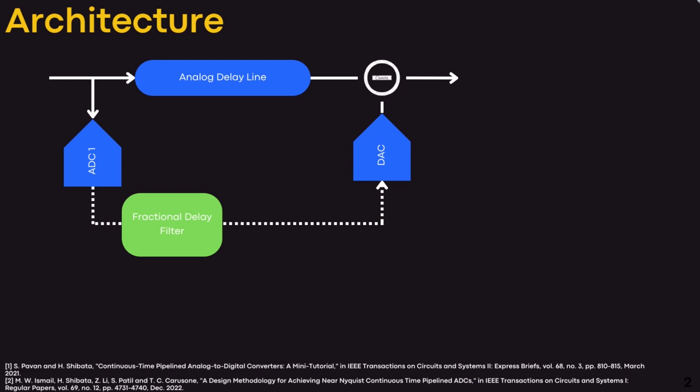As we know, our main goal is to have a higher dynamic range RF ADC. We propose this architecture, which is capable of capturing the quantization noise generated by low precision ADCs and adding it back to have improved precision. In this architecture, ADC1 and DAC1 are the prevailing low precision converters.